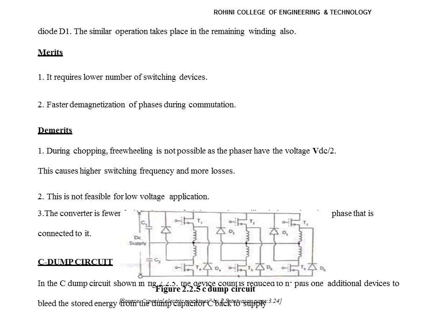The dump capacitor voltage is maintained well above the supply voltage to permit rapid defluxing after commutation. A control failure in the energy recovery circuit would result in a rapid build-up of charge on the capacitor. If protective measures were not taken, the entire converter would fail from the over voltages.